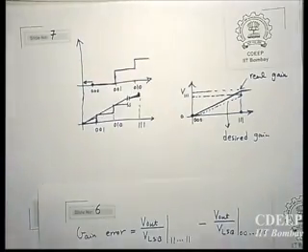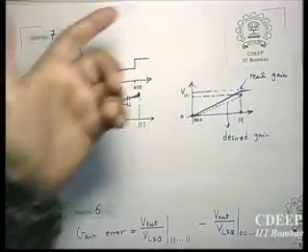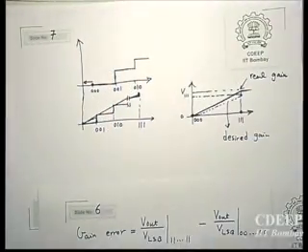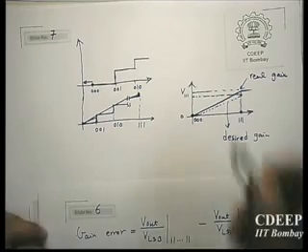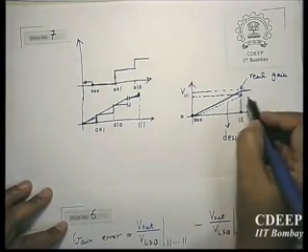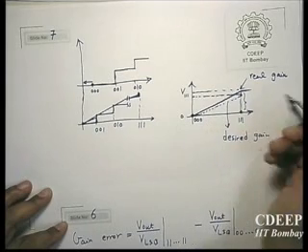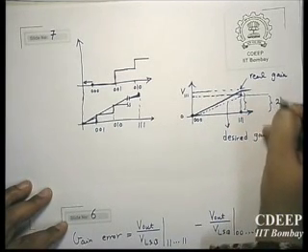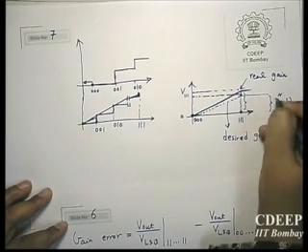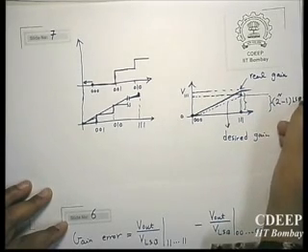That is the slope. Yeah, we are not looking at the absolute value. We are looking at the gain. Means that this value is expected to be 2 to the power n minus 1 LSB size.